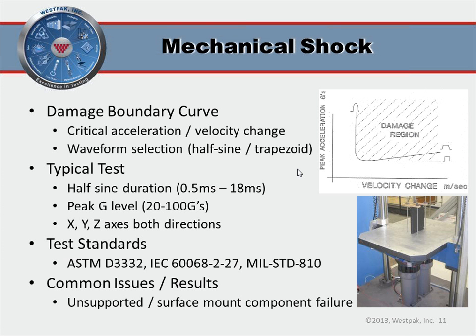Hi Herb, this is Greg. We have a question. This person's interested in constraining units during damage boundary testing. Some folks say to hold the unit or the product rigidly along all surfaces. Some say it should be constrained as it is constrained in the package, but you don't always have that at the prototype level. The question is, the first fully constrained case, is that more severe or less severe on the product?